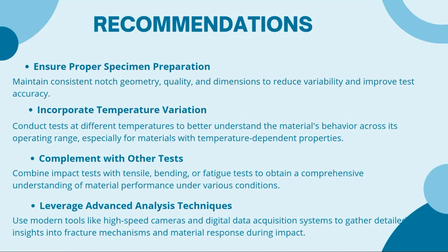Recommendations for the impact test. The first one is to ensure proper specimen preparation, such as maintaining consistent notch geometry, quality, and dimension to reduce variability and improve test accuracy. The second one is to incorporate temperature variation.